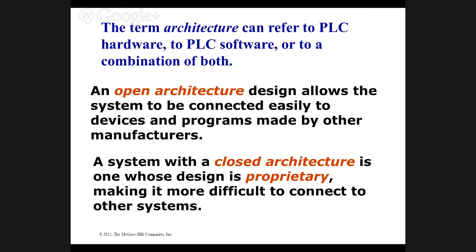Now, sometimes you hear the term architecture, and architecture basically refers to everything in your PLC system. Open architecture allows the system to be connected to other devices and manufacturers. Now, when you're talking Allen Bradley, they are going to an open architecture system, but the old stuff was pretty much, if it wasn't Allen Bradley, it wasn't going to talk to the SLC very easily.